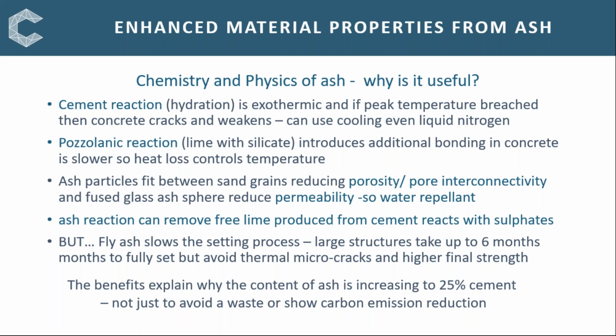The benefit of fly ash is especially seen when forming these large continuously poured concrete structures, such as for dams and foundations of buildings.